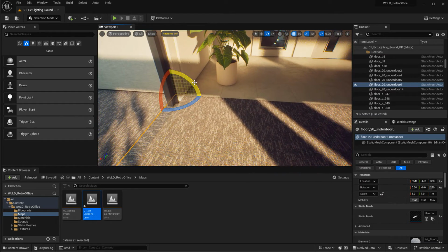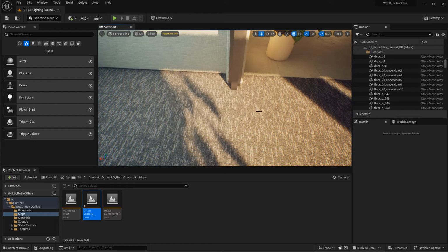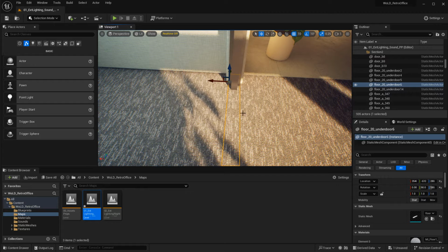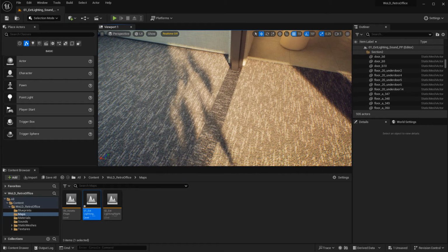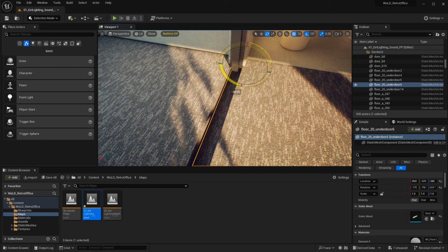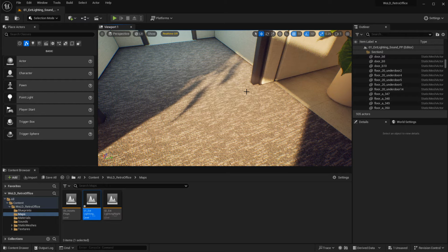So the way you fix this is you simply take that piece of geometry and rotate it 90 degrees until you get a seamless transition from one texture to the other. Once you position it and it doesn't have that seamlessness, just take that piece of geometry, rotate it, and reposition it back. If you can see that it's completely discolored, take it again and rotate it 90 degrees again, then move it up. One of the rotations on certain sides will work.